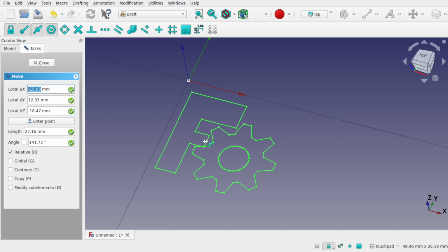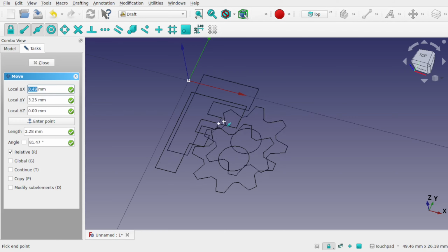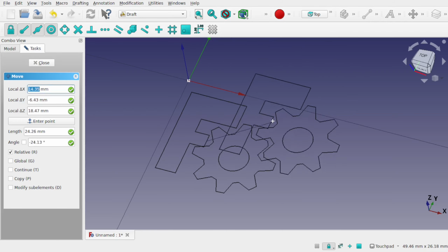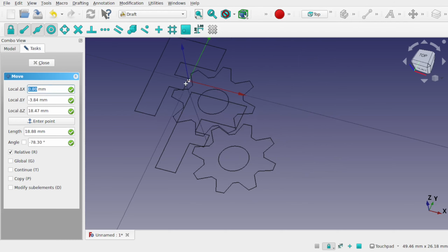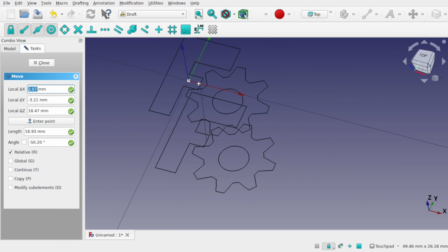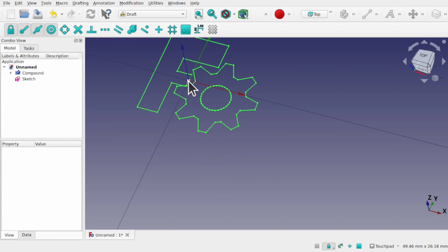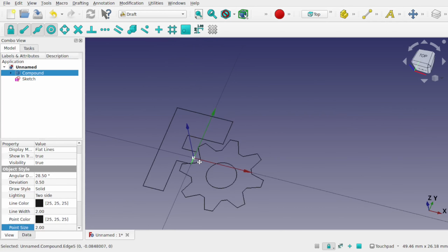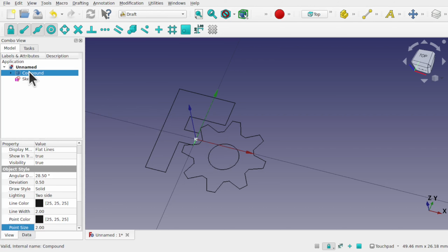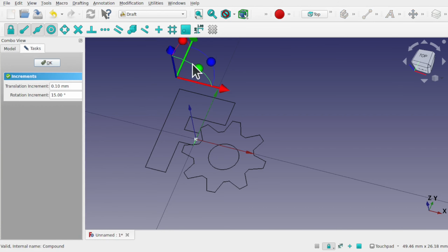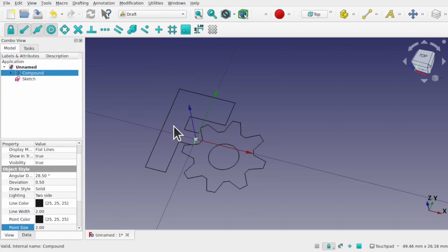So let's hover over and snap to the center of this line and click once. So now if I move the mouse, you can see we've picked that up at that point. If I hover over this point here, I can drop it and snap it to the center point. So this point, which is just a single sketch. And this is the reason we created this sketch. Let's click once. That's now moved, but we haven't fixed the transformation point yet. Come up to compound, right click transform. You see it's still up here. That's okay. Now we've got this moved, we can fix that point.